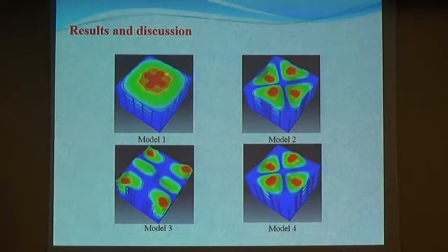The first has no shear wall, and the critical point is here. But when we have the quarter, the distribution of the settlement is greater, and we can conclude that with model 4, where the shear wall is divided into 4 parts, even the roof will be more stable.